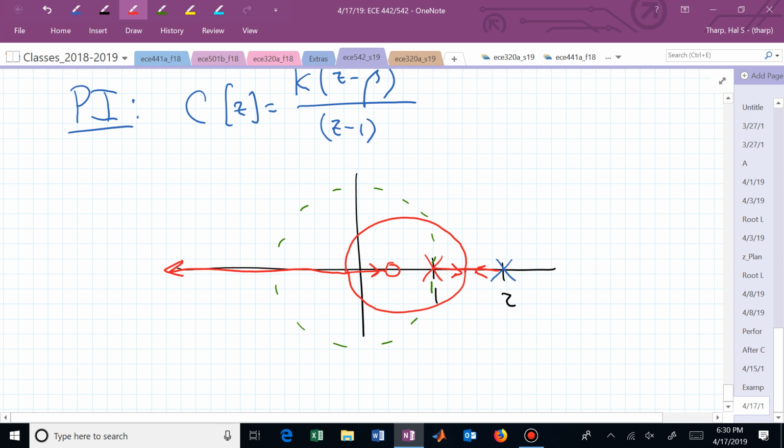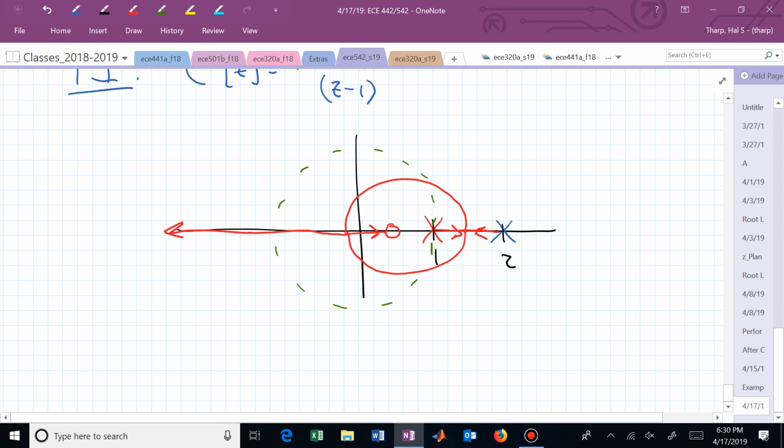And now we have that for our design. And how do you, well, what have I done? I've tried to select the 0 of my PI controller. I've tried to select beta to produce a desired root locus path.